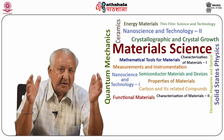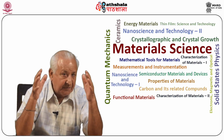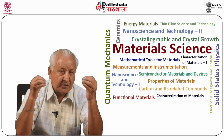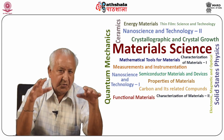The basic system is almost the same as that of Czochralski's system. However, the difference lies in the fact that in the Kyropoulos method, the seed is brought into contact with the melt as in the Czochralski method, but is not raised during growth.